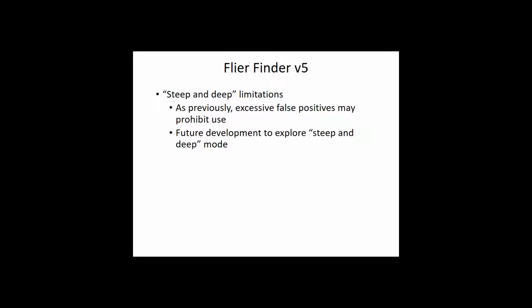So that's going on. In the meantime, what you can do is always fall back to your traditional methods of grid review, all those things that should be being used all along, but just rely solely on those. I know we had talked about this offline, but if you're getting a lot of flyers in certain areas, it may be worth it to just go ahead and brute force data clean, which I know is not an option that a lot of people like to do. But if you're finding that you need to have these constant cycles of recomputing your grid, that's not a great scenario either.